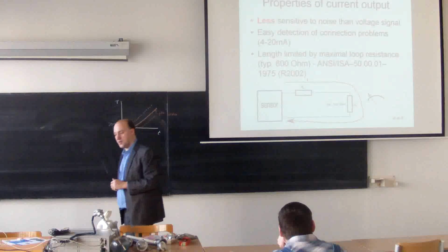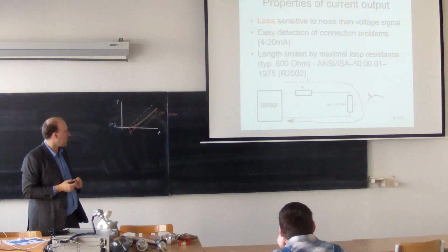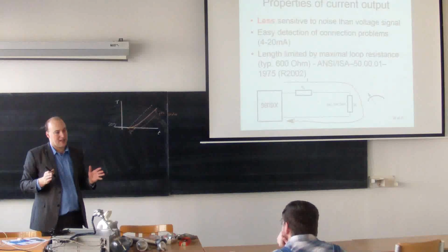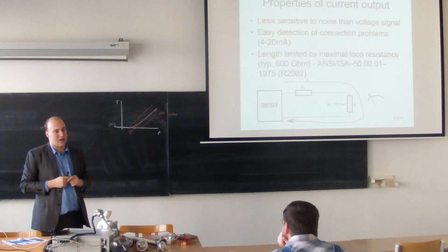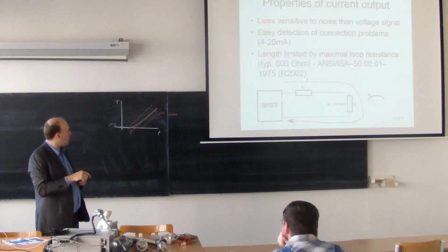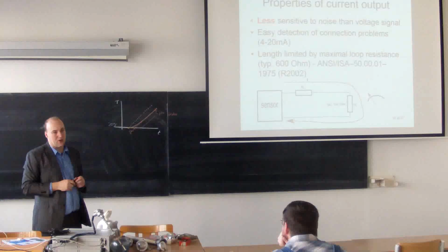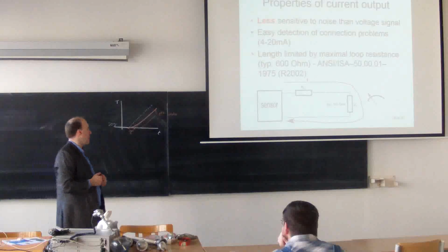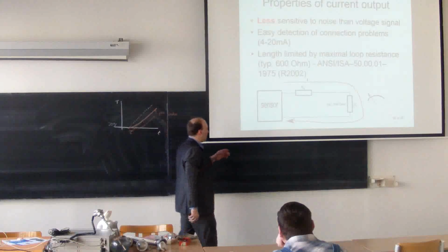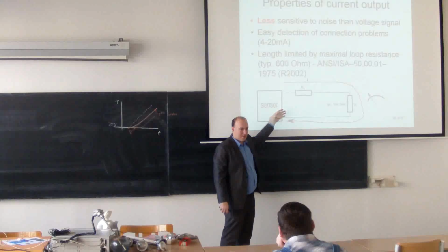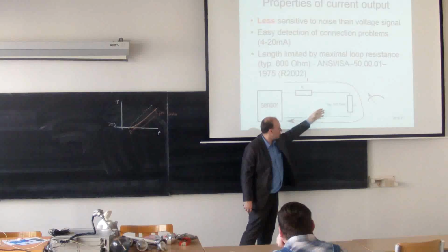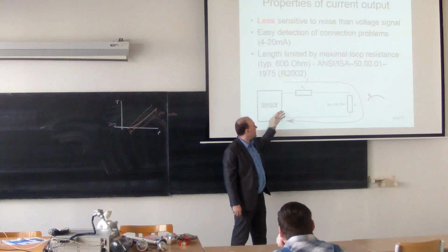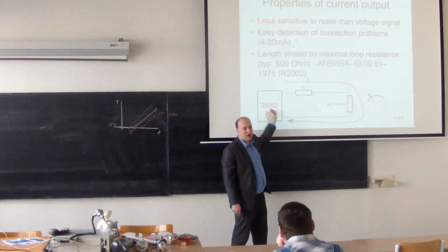There is also one disadvantage. It is limited in the length that you can connect between the sensor and the output. Why? Well, how do I achieve some current in the loop? If I want to push some current through the loop, I need to change voltage on the output.